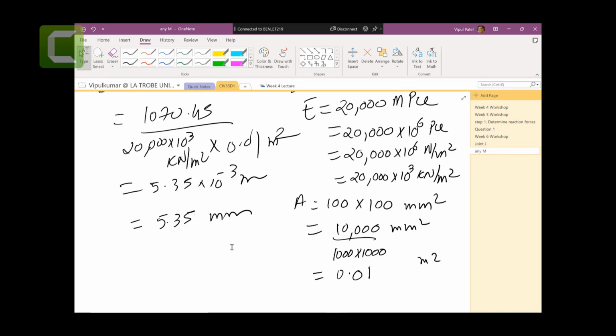We are recording in case you want to go back and check these calculations. Any questions? If you have a truss problem given to you in the virtual work system, you do the real system, find N1, N2, N3, N4, N5, N6, depending on how many members you got. You put the virtual load at the point where you want to find the displacement, in the direction of the displacement that you want to find, and remove all the real load and find n1, n2, n3, n4, and so on.